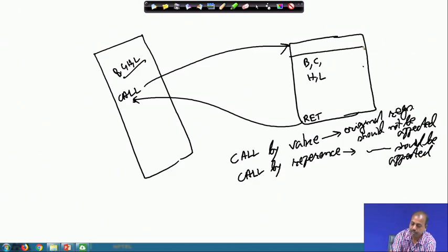Then the first few instructions of this subroutine should be push B and push H. They will be saving those two registers, and before the return instruction, I should pop them out, using instructions like pop H and pop B, so that the values are restored. So, the original content of the B, C, H, L registers is not lost.